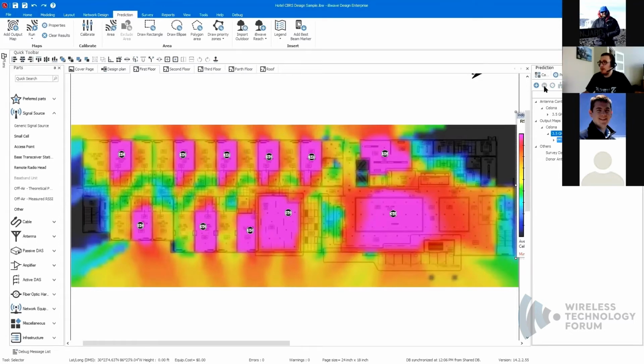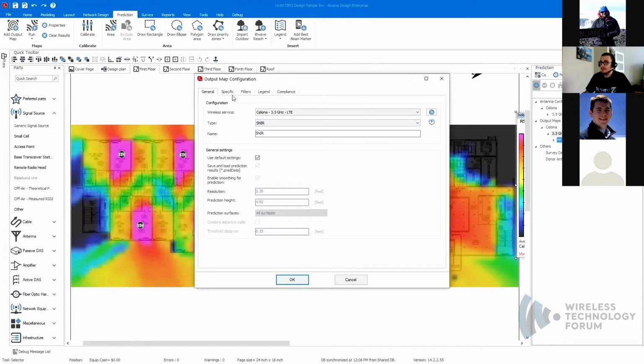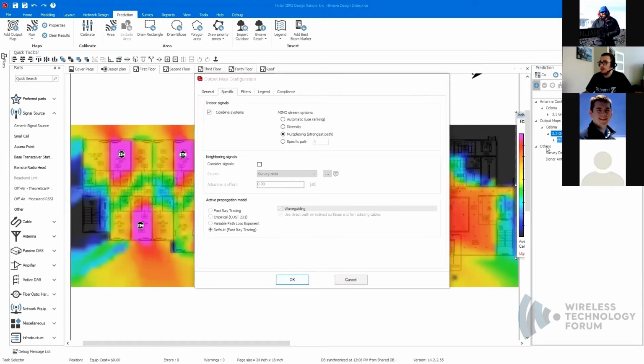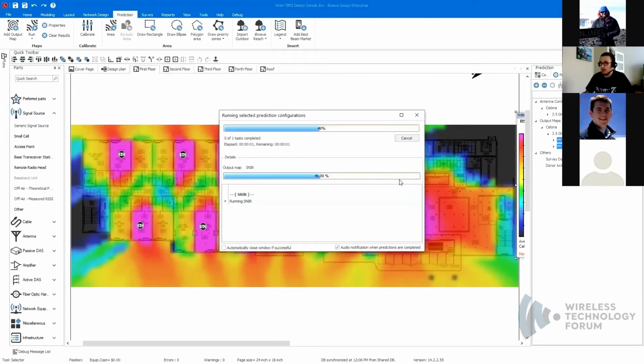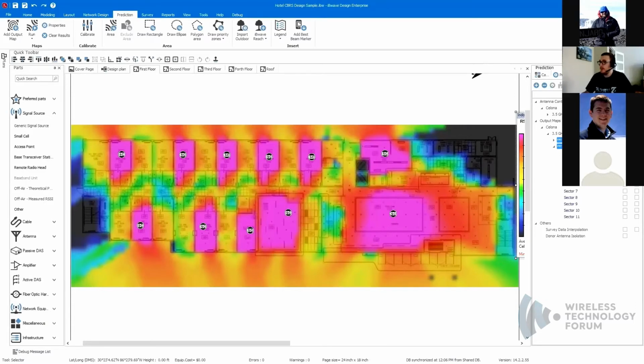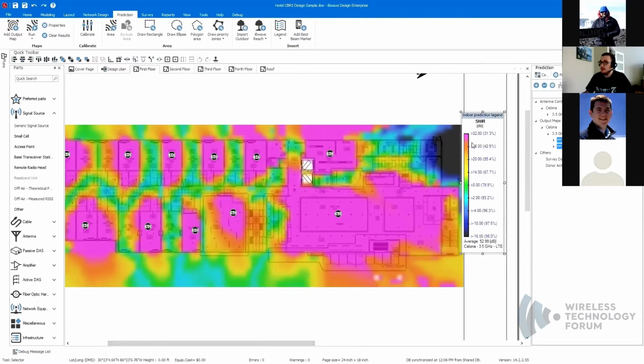And the other most important map is the SINR map. So if I go to SINR, combine the system again, and again, this is the worst case scenario. We only have one channel that we can reuse. In the ideal scenario, you would have multiple channels that you could reuse, the same as in Wi-Fi. So this is my channel, my SINR map. You see when you are close to the small cell itself, the SINR is good, like 30 dB or higher. As soon as I get between the small cells, the SINR degrades. It's closer to 8 and then degrades all the way down to 2.